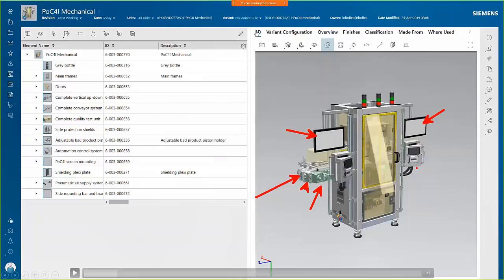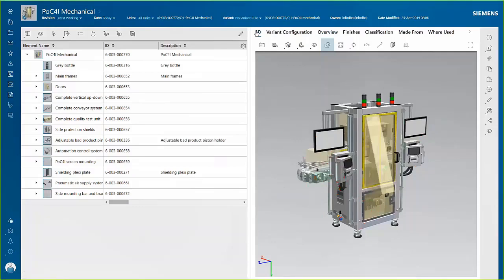There's a couple HMIs. So there's one on the left, one on the right, and the position of those is determined by what the conveyor looks like. So if that conveyor is bent forward, it's a little tough to have this HMI right here. They'll collide into each other. So I have a little different angle on that particular HMI. And not shown very well here, but there's also some different door choices as far as what that door needs to look like. So in essence, right now you have a 150% BOM, and you're able to visualize what that 150% BOM looks like. You can't build this thing because you can't have two parts occupy the same space.